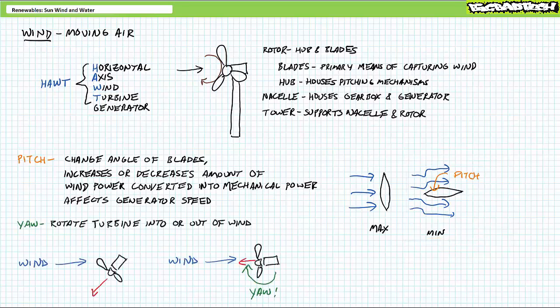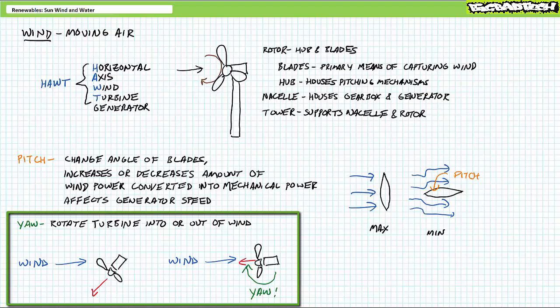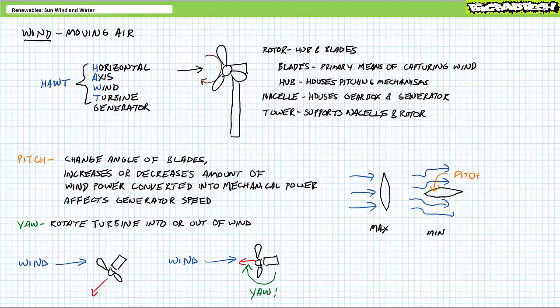Additionally, the efficient capture of wind power necessitates that a modern wind turbine generator be pointed into the wind. This necessitates that a wind turbine know where the wind is coming from, where it's pointed, and have actuators known as yaw motors to effectively close the distance between the two. Turning a wind turbine generator into the wind is known as yawing. Pitching and yawing mechanisms, as well as other accessory mechanical and electrical systems, can additionally serve to de-energize the wind turbine for purposes of repair and service and emergencies. We'll examine wind turbine pitching and yawing systems and much more in greater detail in later lectures.